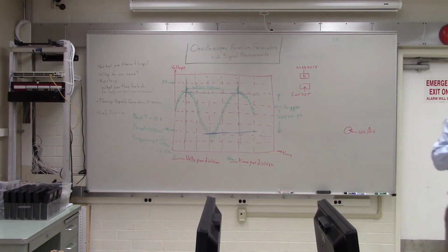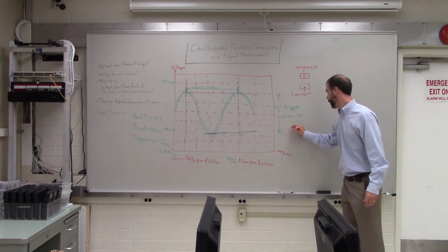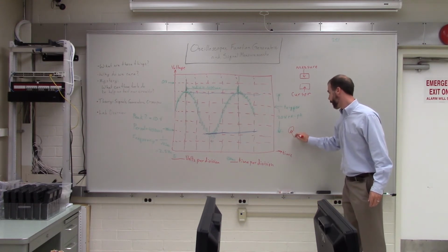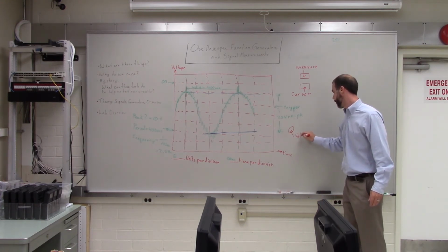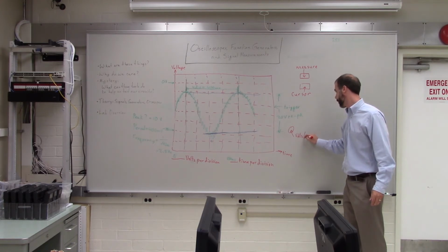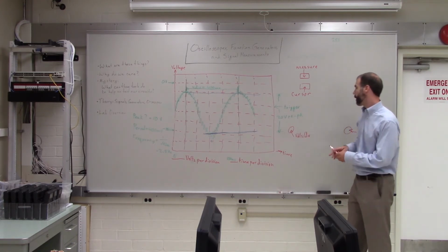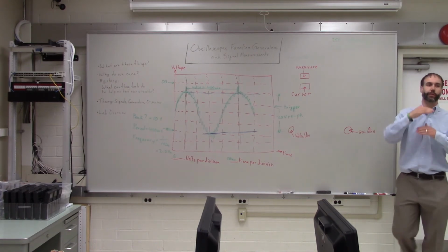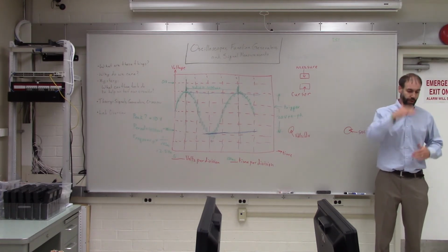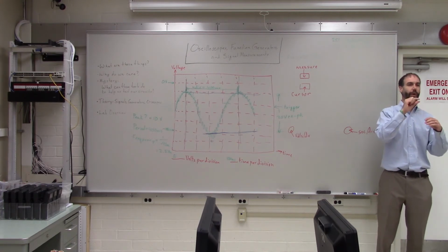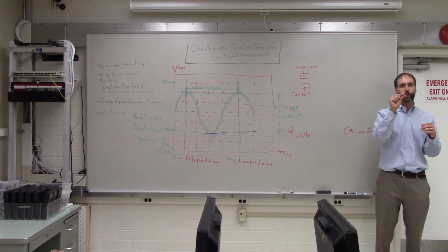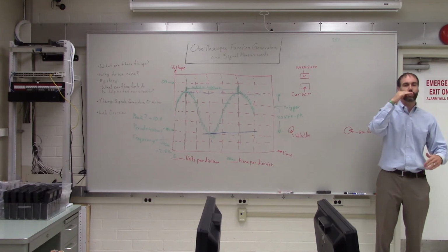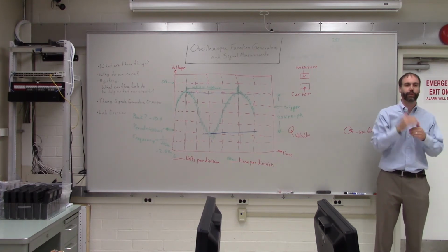So for each signal, there's a knob that is labeled volts per division. And these knobs are like zooming in and out in the vertical direction. So you can zoom way out and you can see the whole signal, and then if there's one part that's particularly interesting, you can zoom way in on that part and just get a much bigger picture of that part.